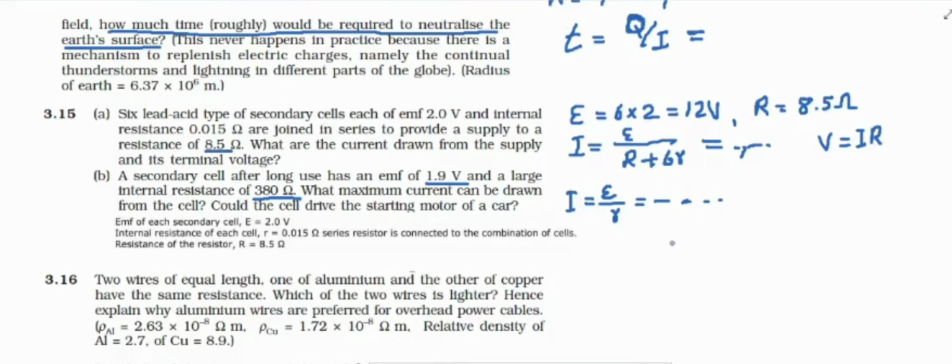So this small dry cell of 9 volt having high internal resistance, capital R is high. Therefore, it can give only very less amount of current in terms of milliampere. But if the car battery of same voltage, you can see its internal resistance is very, very small. Therefore, it can give very high current.